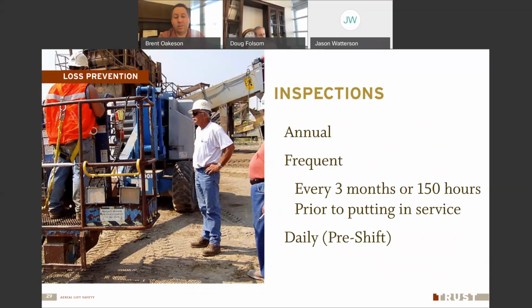But it's also critical that you do that daily pre-shift inspection. Again, you don't want to take a chance. You don't want to put your guys in there or yourself in there to go up in the air and have hydraulics fail or something break and have something come down. And that's why it's really important to do those inspections.